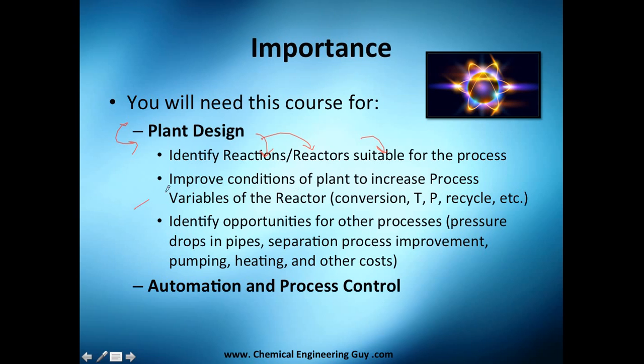Also, you need to do some improvements, change the conditions like temperature, pressure. Maybe you want to work with less recycle because you're having a lot of cost pumping that recycle stream. Or maybe you want to increase conversion. So the thing here is that you're going to be playing with a lot of variables, and if you don't know how to operate or how reactors work, you will not be able to move conversion, temperature, selectivities, all that. And that's only about reactors.